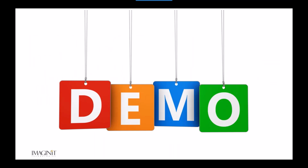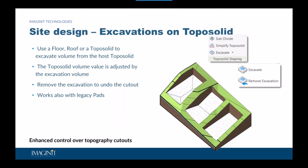The next demo will be going over site design excavations on a Topo solid. With Revit's new site design tools, we will create an excavation on a Topo solid using a floor. This new feature will allow the use of a floor, roof, or another Topo solid as cutting elements to excavate a Topo solid. The volume reported by the host Topo solid is adjusted as the element is excavated by other elements. Remove the excavation to fill the excavated volume. The element used to excavate, such as the floor, will remain in the model. You can use the legacy pads as a cutter geometry to excavate a Topo solid.